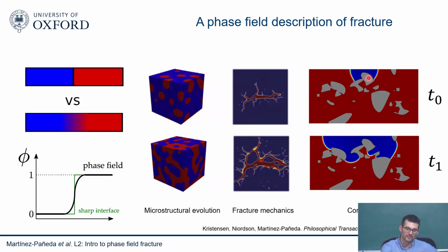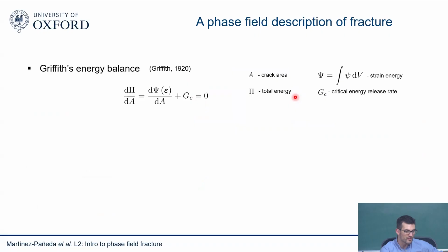But yeah, very powerful technique that is revolutionizing many areas of science and engineering. And I think the good thing in fracture mechanics is that not only does it allow you to model complicated cracking phenomena, but it allows you to do so in a scientifically sound way. So in a way that is physically sound, that is in agreement with the thermodynamics of fracture, with well-established fracture mechanics theory. So again, if we think back to Griffith, what we just saw in the previous lecture, is that a crack will grow whenever the energy stored in my material is equal to or larger than the critical energy release rate, the fracture energy, my material toughness.